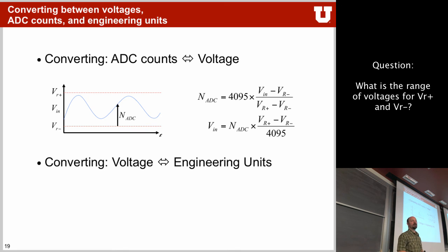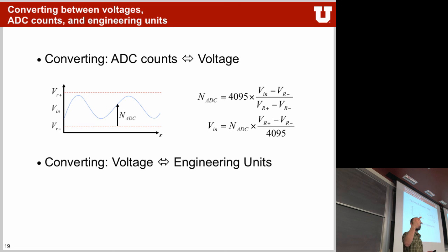They don't have to be negative, but usually you have two reference voltages. The minus is the lower one, the plus is the higher one. So they can, for example, be 1 volt and 2 volts, right? Sometimes, yes, the negative voltage can be a negative voltage, like it goes into the negative. But more often it's something positive. Most of the times, VR minus is actually ground, and VR plus is VCC, but that's not always the case. Sometimes you can actually change it and give different reference voltages. So this is how we get from ADC counts to voltage.